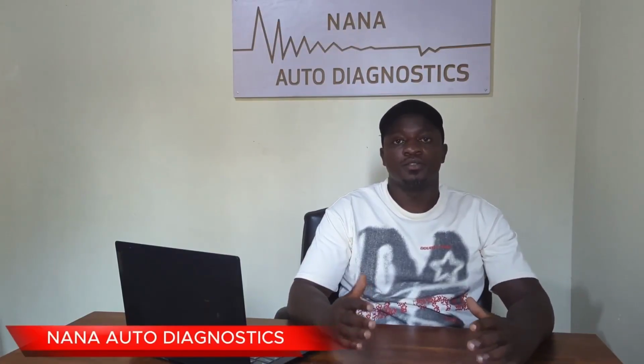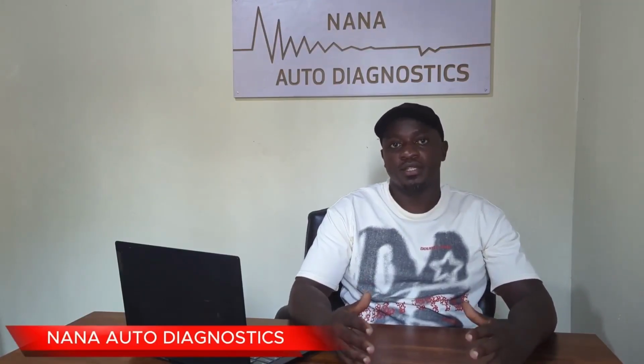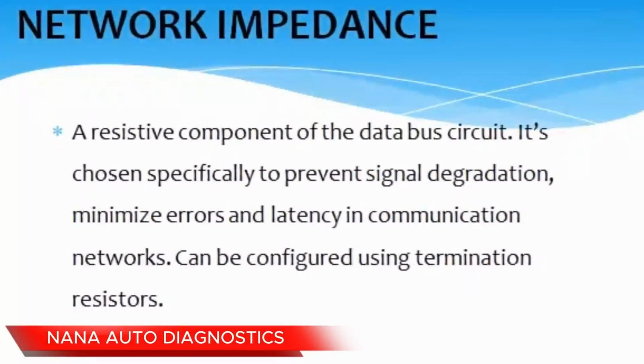Impedance refers to the total opposition of alternating current in any given circuit. It has two parts: the resistance part and the reactance. Now reactance is the opposition to the flow of AC in either an inductor or a capacitor. So as it pertains to automotive communication, I will define network impedance as a resistive component to the data bus